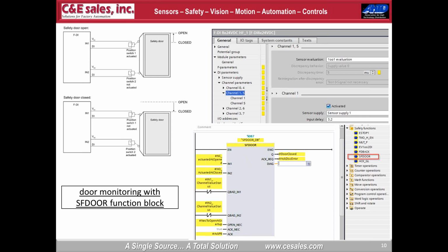Rather than using one out of two dual channel inputs, it can use any two 1 out of 1 inputs. They may not even be on the same card. Probably the other feature in the connection that you might keep in mind with using it like this is you probably want these internally sourced, just to get a little protection of the actual wiring to the switch.